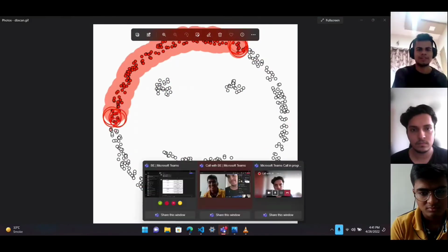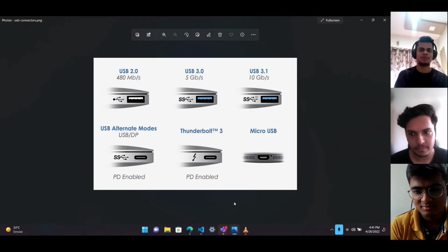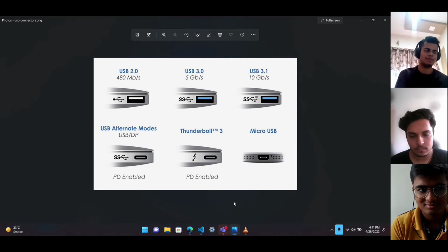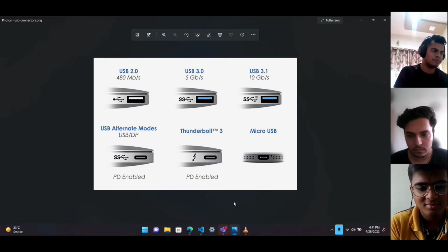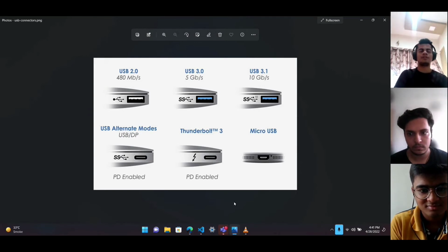Thank you, Arjun. Now let's talk about the hardware implementation of our project. For a machine vision-based project, we have used several communication protocols. One of them is USB 3.0. USB 3.0 is used as the interface for a camera with the main computer. USB 3.0 builds on the USB 2.0 architecture by increasing its speed to 5 gigabits per second. USB 3 is also one of the three main popular machine vision standards, which are Gigabit Ethernet, USB 3, and CoaXPress. Within these standards, we found USB 3.0 to be the best because it is easy to work with and it is commonly available right now.